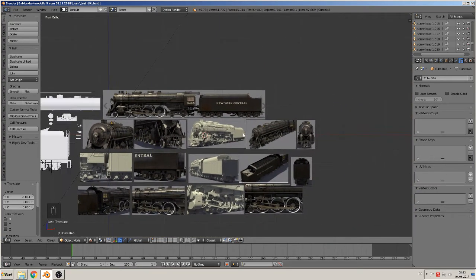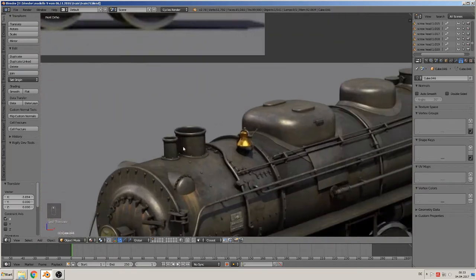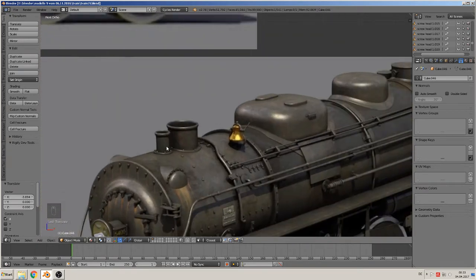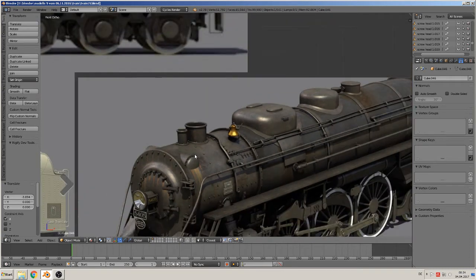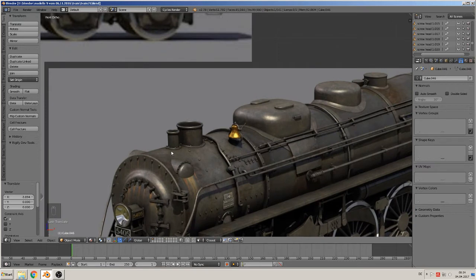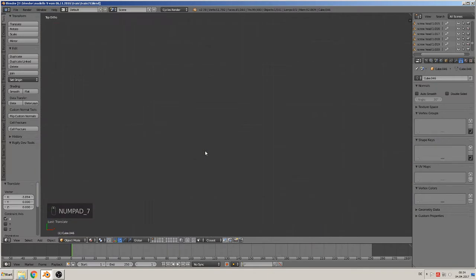when you look from the top, you see that around these cylinders are big pieces, but this is bent with the roundness of this great cylinder. So there are two possibilities to do something like that. The first is to make it with a shrink modifier to shrink it on the great one, but then you need many vertices, or you can cut it and then extrude it out. I will make it with cutting.